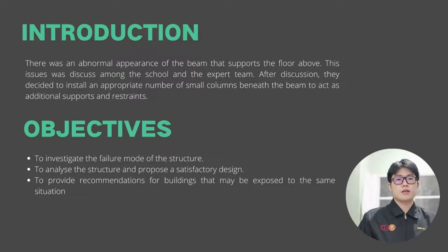Then, a meeting was held immediately with the management team, the members of the PIBG committee, and the technical expert to discuss the following issues. Finally, they reached an agreement where a consultant team was appointed to help in investigating the situation, and the consultant team then decided to install an appropriate number of small columns beneath the beams to serve as additional support and restraints.